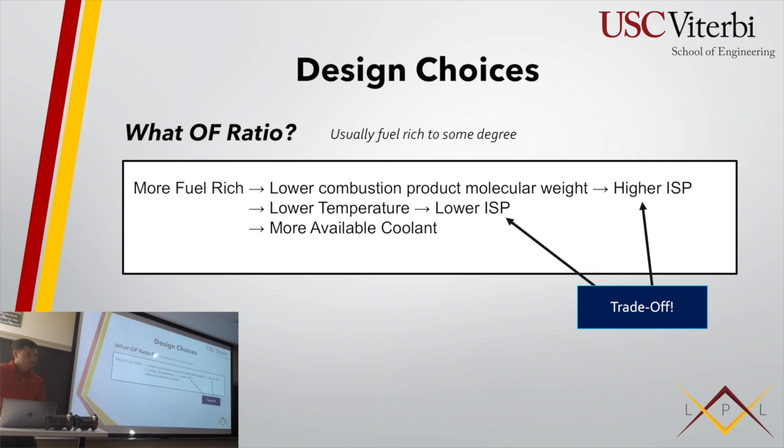Wait, I'm sorry, could you say that again? Yeah, so the OF ratio, if you have more oxygen, then it's going to be hotter, because when they combust with each other, it results in a hotter temperature. That's why film cooling is literally you blast something with fuel, like a little barrier, because then when that area combusts, there's more fuel than oxygen, and so it's not as hot as when it's not.